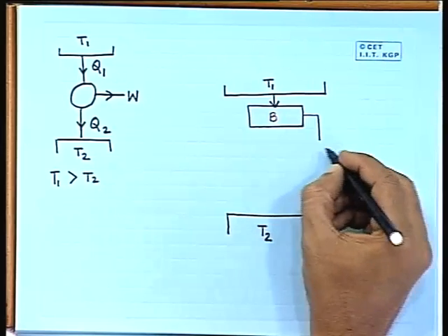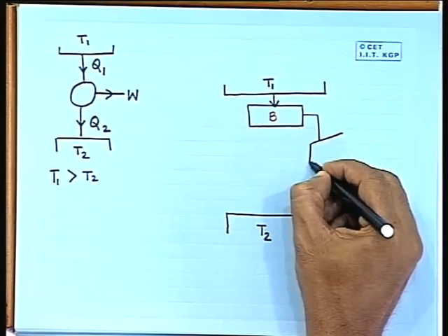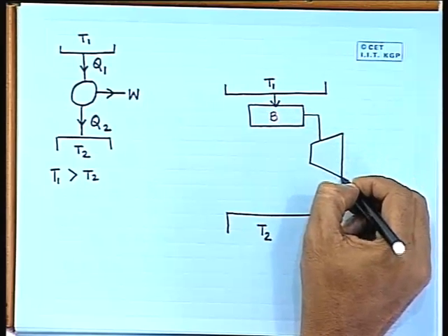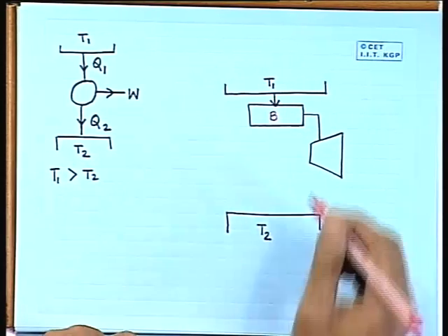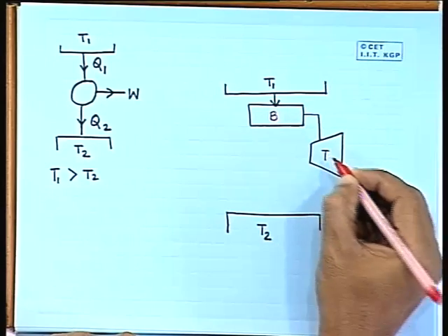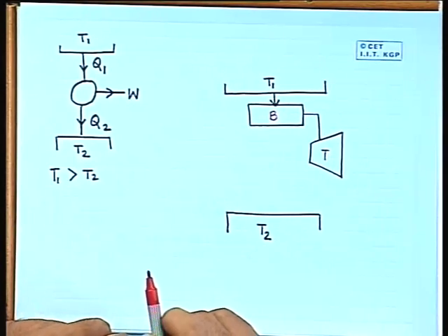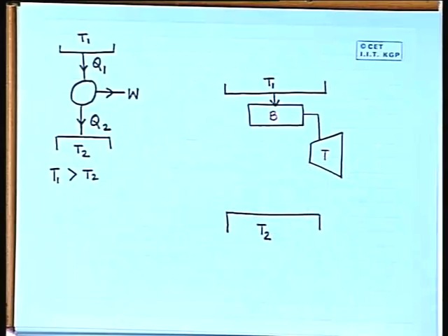there is expansion of the fluid and it is doing a certain amount of work. So, the next component which I am drawing represents a turbine. It is doing a certain amount of work, and in this process the fluid temperature is also falling. As there is change in temperature in this process, there should not be any sort of heat transfer, because along with temperature change, if we have heat transfer, then the process will become irreversible. So, basically this is an adiabatic expansion of the fluid.